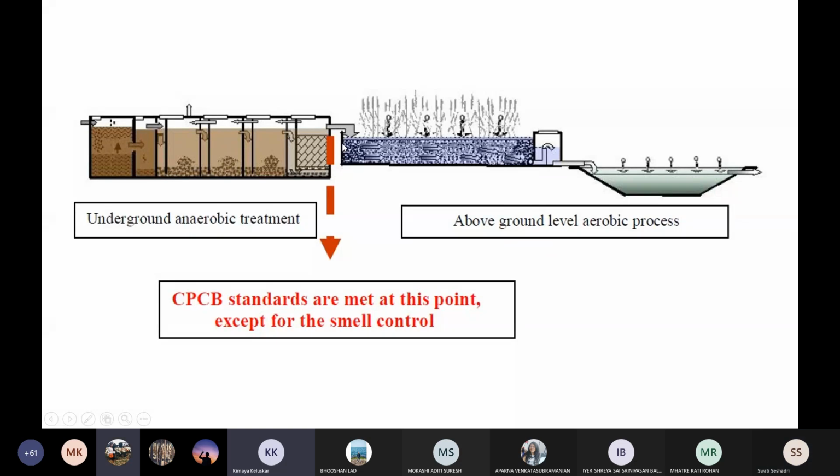I have a question, please. Go ahead. When you say the underground anaerobic treatment bed has to be 80% of the OHT, is it just the septic tank or the entire brown box that you have shown? Entire brown box. The first one, the septic tank along with the other anaerobic treatments. So this one is a settling tank with all your treatments. Okay, thank you.